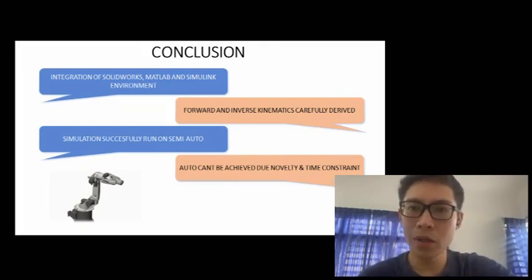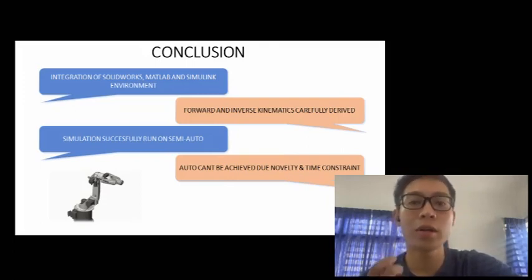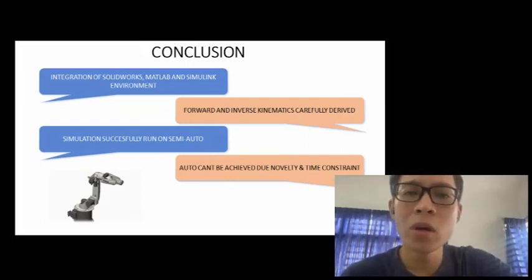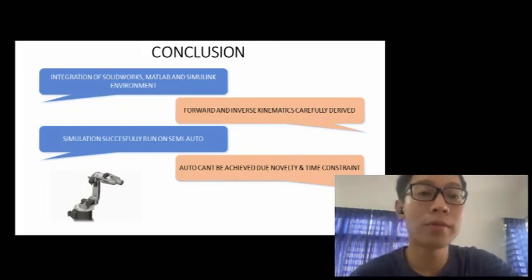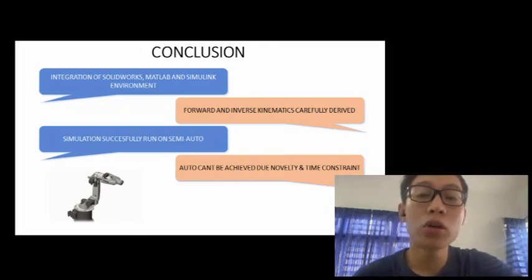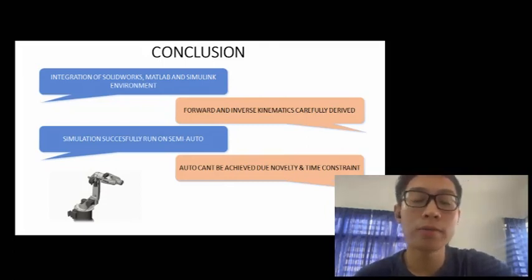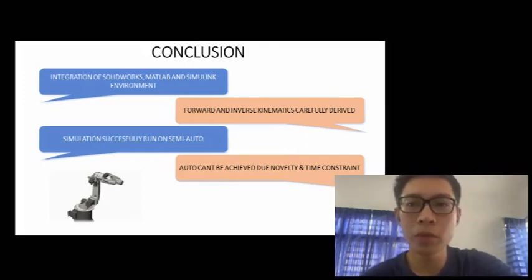Theoretically, when every coordinate is keyed in based on the XY plane for every word, the algorithm will figure out which joint is to be rotated by a certain degree. All this is thanks to both forward and inverse kinematics derived earlier. So the arm will move accordingly within the workspace derived in MATLAB, following the path left by our initials, as previously mentioned.